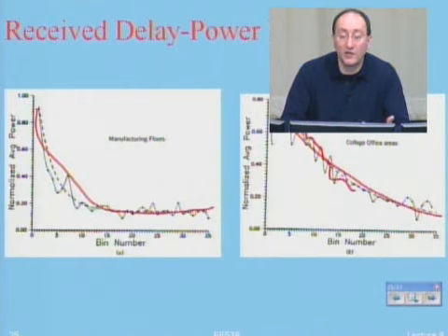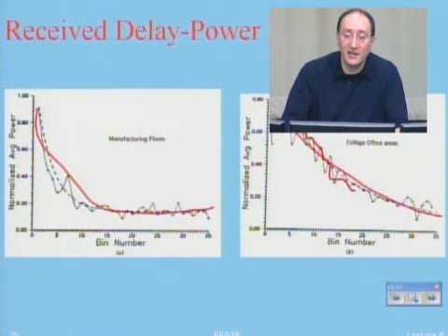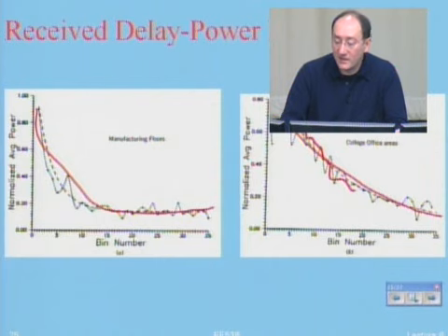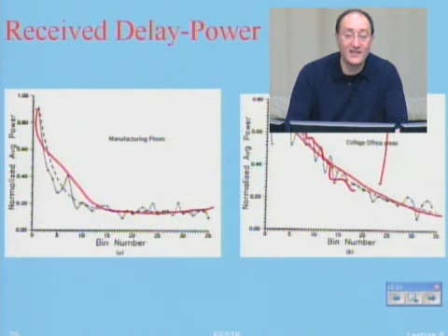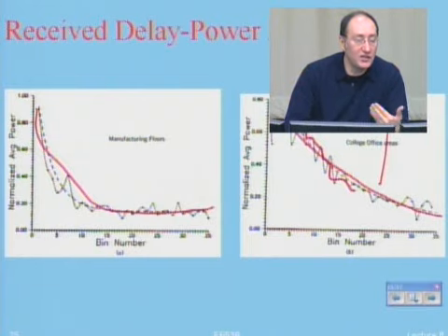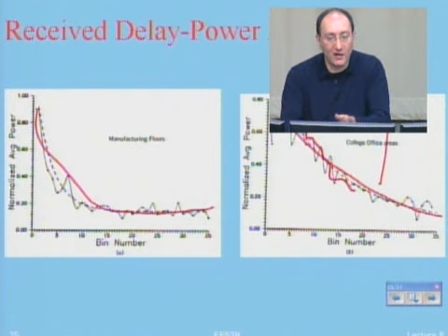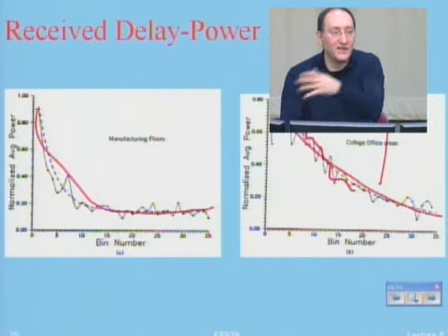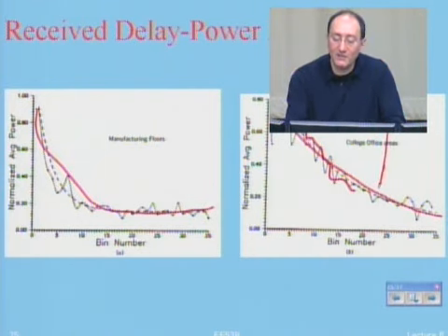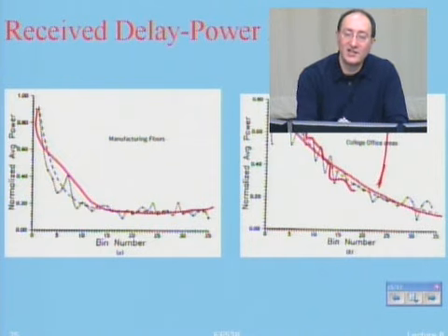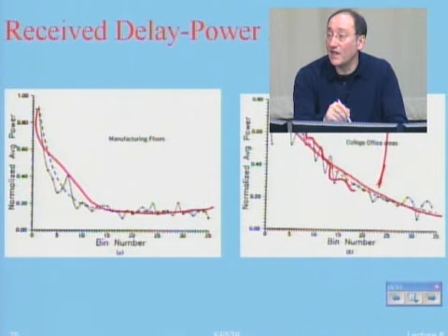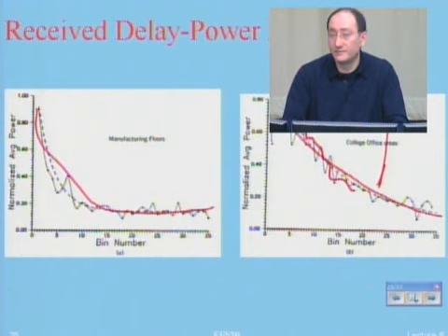In the received power versus delay, the delay power spectrum, which validates what we have in the 802.11b model, for example. These things are supporting that. If you want to measure the delay power spectrum, you evaluate the power received at different delays in different locations, and you always end up with an exponential, which is consistent with what we have in the 802.11b model.